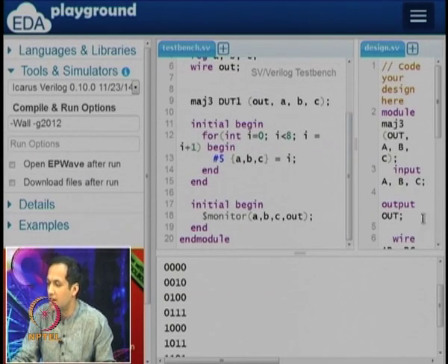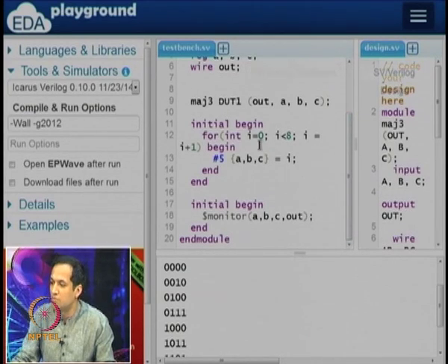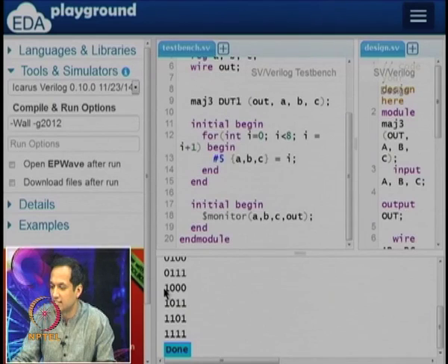There is some evaluation there, whatever the output is, that comes as capital OUT, and that comes back as small case out here, and gets printed out. You can see that whenever there are 2 zeros you will see a 0, if there are 2 or more 1s you will see a 1. So in this case there are 2 zeros and a 1, the output is 0.